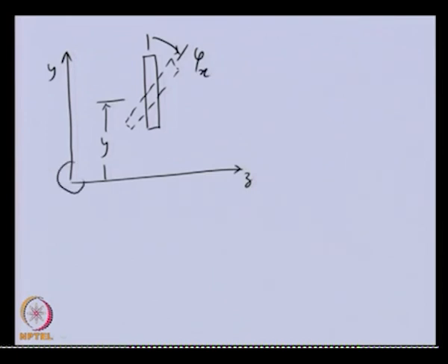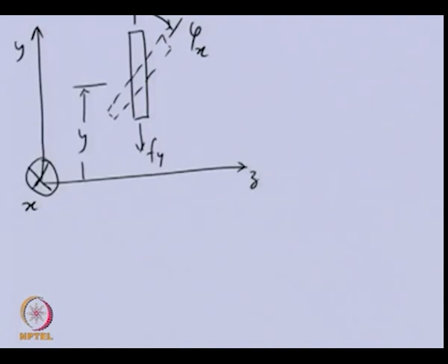The x axis is perpendicular to the screen, going into the screen. So, the cross is representing that we are looking at the tail of the x vector, which is inside the screen. Because of these displacements from the shaft, we will have an elastic reaction force. Apart from that, we will have a reaction moment from the shaft, that will be yz.